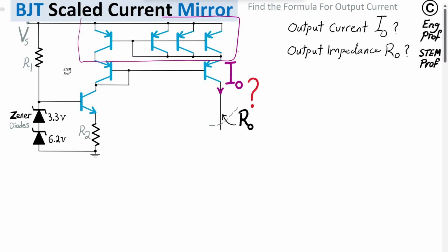To quickly run the analysis, one important piece of information is we need to make sure that these transistors are properly matched so that we have an accurate constant current coming out of the circuit with minimal temperature dependency. So it's important that if we use, for example, packages of 8 PNP, or smaller packages like 4 PNP, then at least we make sure that these transistors are in the same package and these transistors are in the same package as well. But the same type of package.